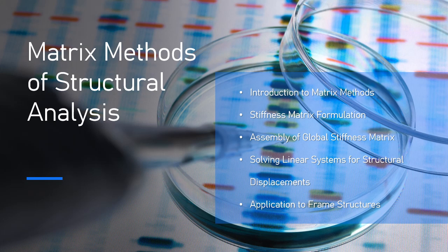3.4. Basic steps in matrix methods. 1. Define the degrees of freedom. Identify the degrees of freedom for each node, or joint, in the structure. This includes the translational and rotational degrees of freedom. 2. Develop local element matrices. For each structural element, e.g., beam, truss, or column, develop the local stiffness matrix that represents the relationship between forces and displacements for that specific element. The local stiffness matrix depends on the geometry, material properties, and type of loading for the element.